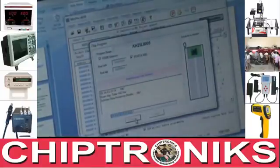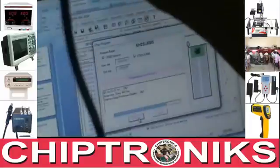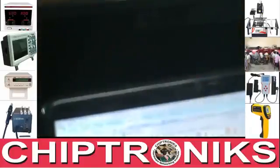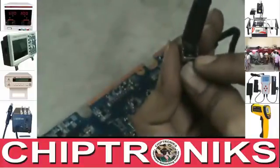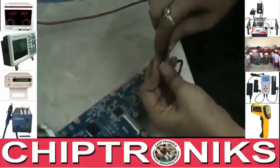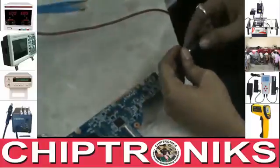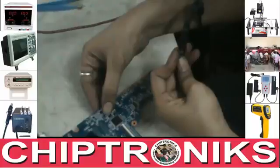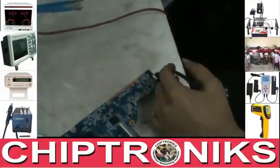One more thing, I'll tell you this. When you check Dell and HP, which use this type of connector, which have an adapter detection signal, when you plug here, one light glows over here. It means your BIOS, EC BIOS is working fine. But when you don't get this LED, it means maybe the problem is in your EC BIOS. That's why here you don't get an adapter detection signal. Okay, here our BIOS is programmed.